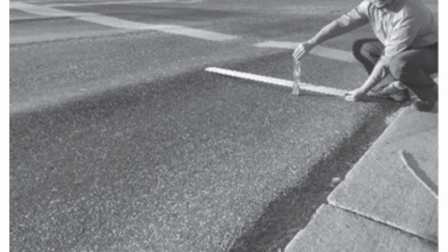Structural rutting is the sum of permanent vertical deformations, densification or deformable materials, of all pavement layers due to repeated traffic loads. It occurs due to less stiff materials and low thickness of layers. Improper compaction or mix design, such as high asphalt content, excessive fines, and insufficient amount of angular aggregate particles are responsible for rutting. Shear rutting is the lateral shear displacement of asphalt materials under wheel loading.